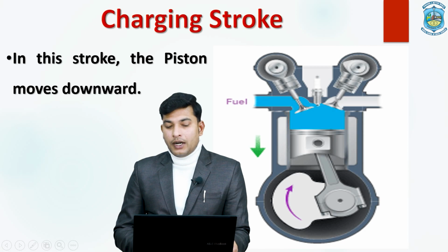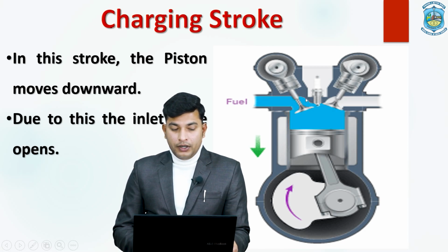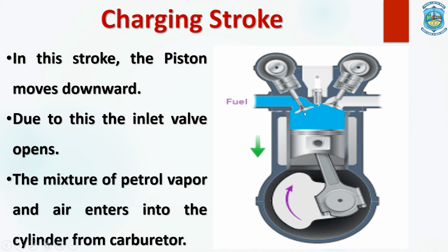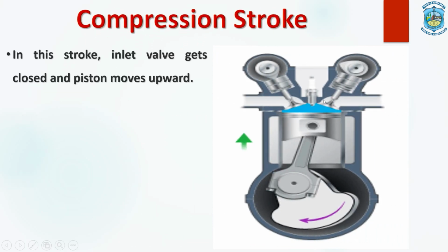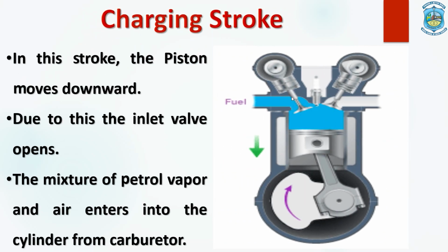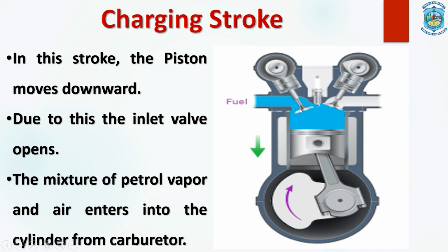So this particular inlet valve gets opened, and the mixture of petrol vapors and air that is coming from the carburetor fills this particular cylinder for the next step. So in the charging stroke, we can say that the inlet valve is getting opened, and the fuel is filling this particular region, and that is ready for the further steps.